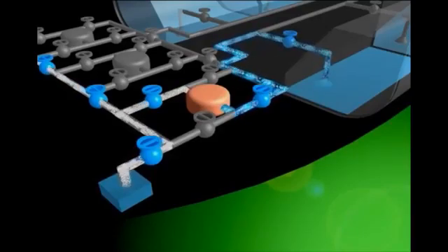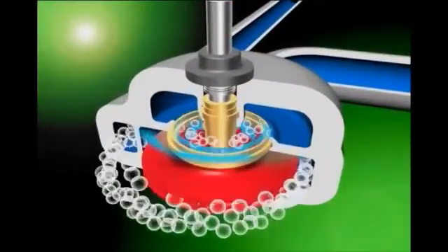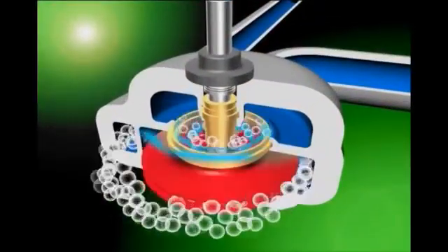If the discharge amount is extremely small, there are cases where unnoticeably small amounts of air gather within the pump and build up to a level that could disable the pump. If left as it is, seawater in the pump will run out, resulting in burn.